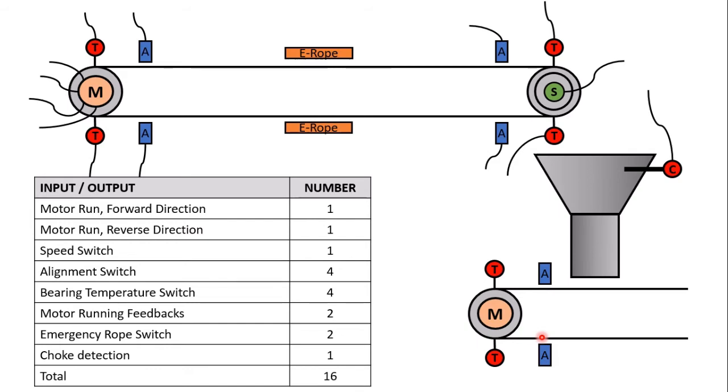Another thing you can say is that to avoid long distances, you can move the PLC closer to the instruments or sensors. But PLC equipment is very fussy when it comes to environmental conditions. I mean, you just have to look at a PLC in the wrong way and it will start giving you errors. Secondly, PLC equipment is expensive, so you will not go and put a PLC rack in an area where there are jet sprays of water or thick charcoal dust.